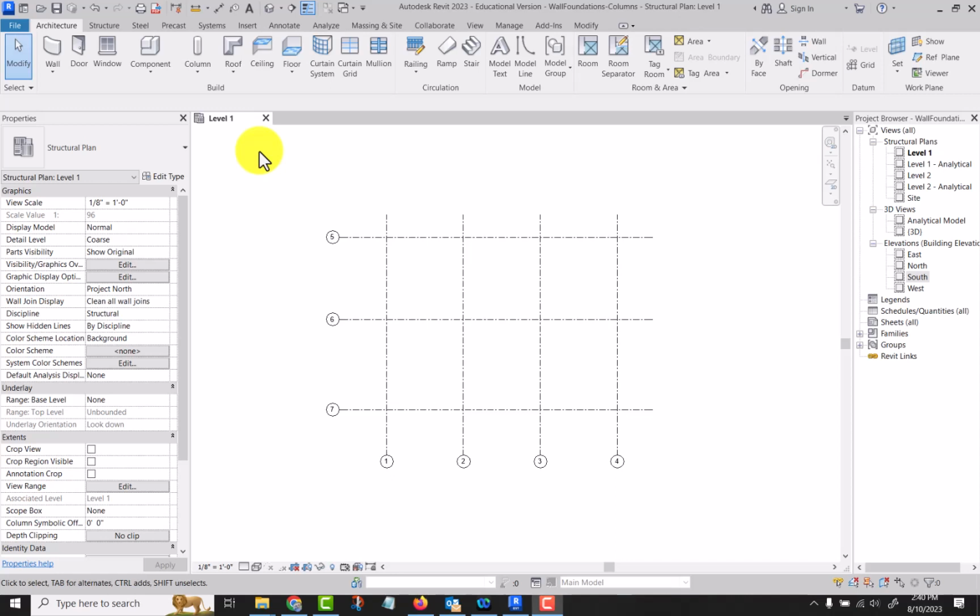Okay, let's talk about columns. You should remember from your print reading class and fundamentals class that columns are the vertical members that hold up a building. Most residential buildings are held up with walls, but you'll still have columns for basements and porches, things like that. You may even often run into some architectural columns inside the building or on porches.